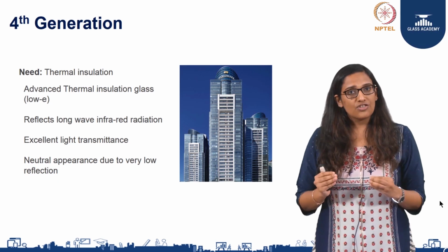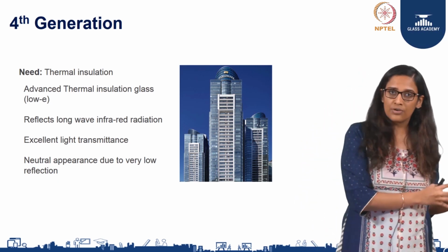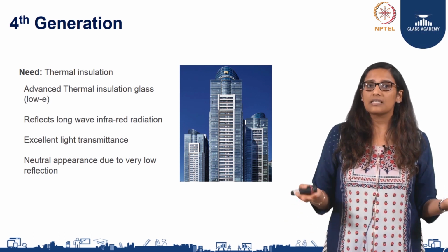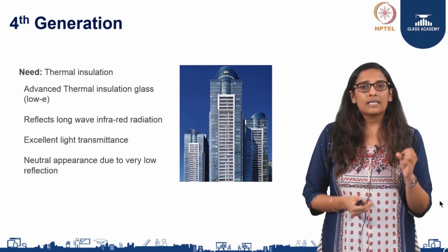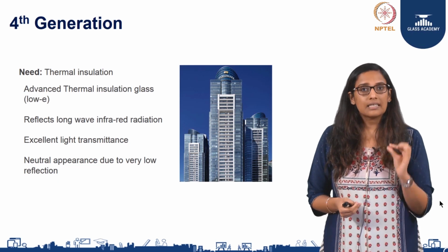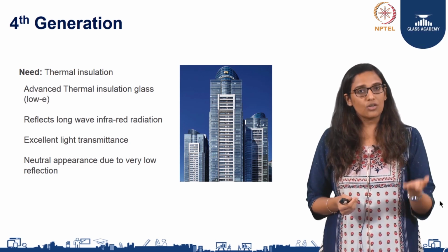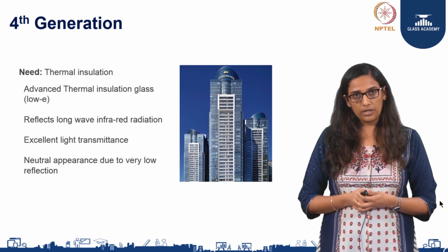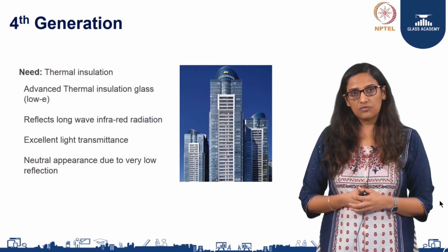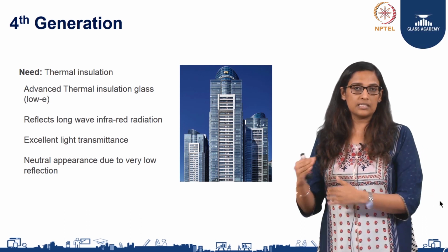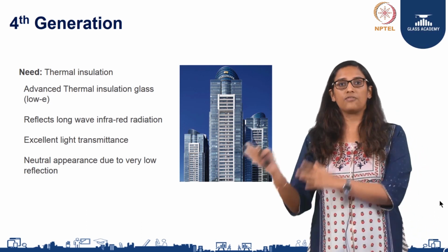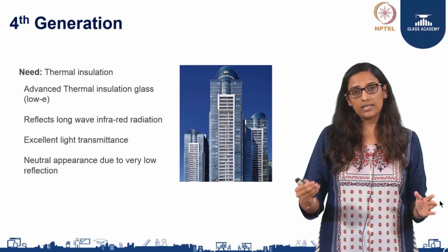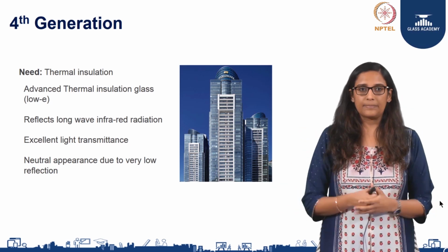The way the fourth generation of products is significantly different from its previous generations is, apart from the feature that it gives a significantly better U value, that this kind of coatings contain a precious metal called silver. The fourth generation product has one layer of silver which amplifies this performance significantly from the third generation and gives a strong solar insulation, thermal insulation property.